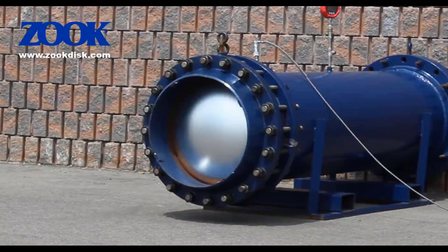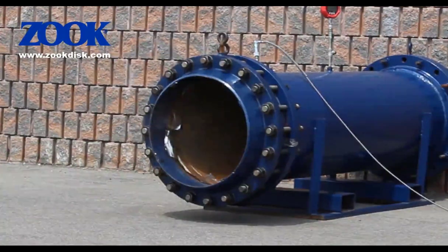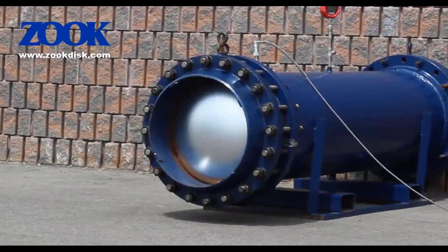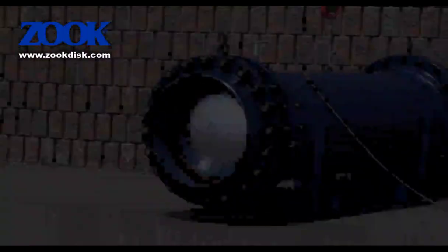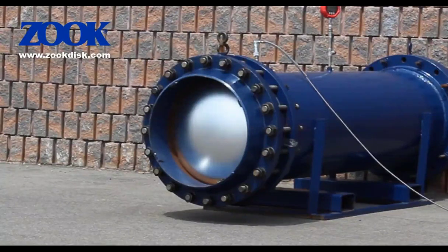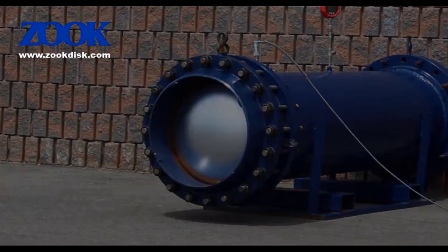Here you can see a rupture disk mounted to the end of a chamber, which is sealed at one end and a rupture disk mounted on the other. Pressure is introduced into the chamber and the disk bursts or opens when the pressure differential reaches a set point of the disk. Differential pressure simply means the pressure on one side of the disk is higher or lower than the other. If we pressurize both sides of the disk equally, nothing would actually happen.